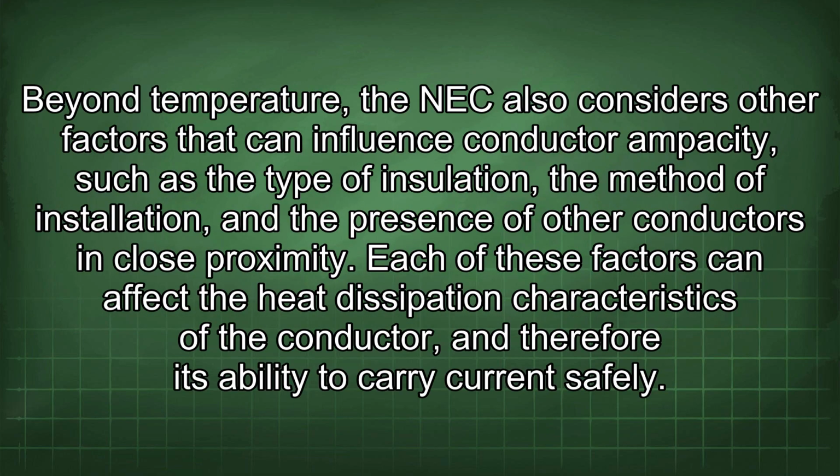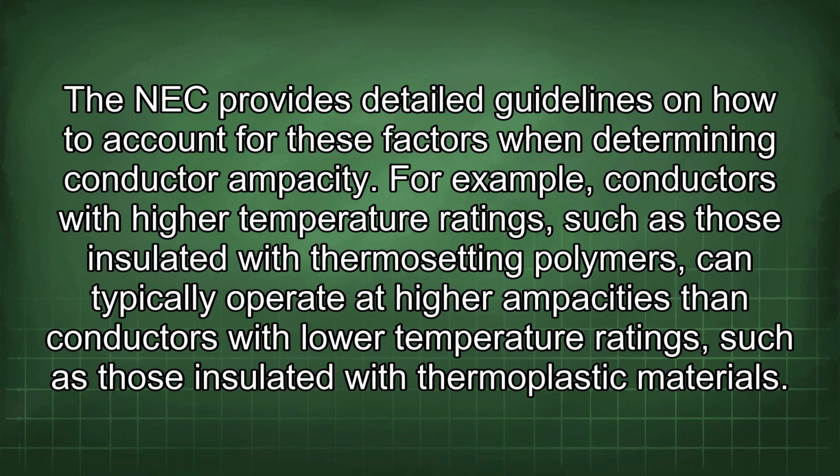Beyond temperature, the NEC also considers other factors that can influence conductor ampacity, such as the type of insulation, the method of installation, and the presence of other conductors in close proximity. Each of these factors can affect the heat dissipation characteristics of the conductor, and therefore its ability to carry current safely. The NEC provides detailed guidelines on how to account for these factors when determining conductor ampacity.